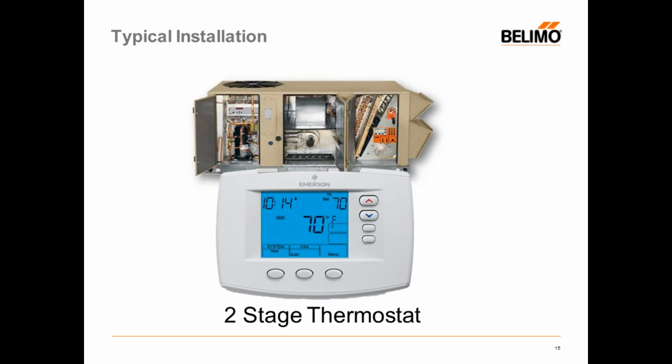We get a lot of calls on this particular requirement. You can use a 1-stage thermostat, but you lose the code compliant functionality. You will no longer get free cooling, and you only get integrated cooling. So don't use a 1-stage thermostat.